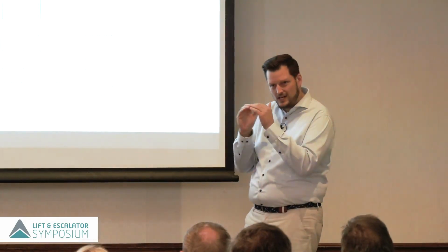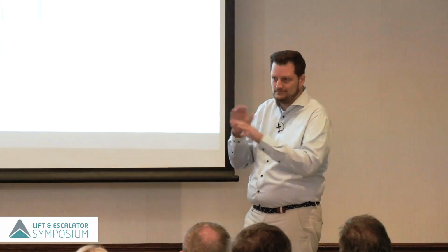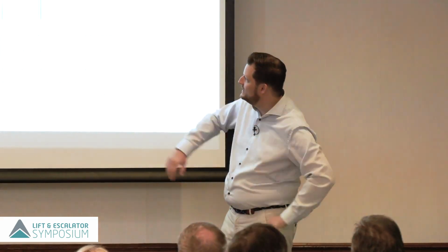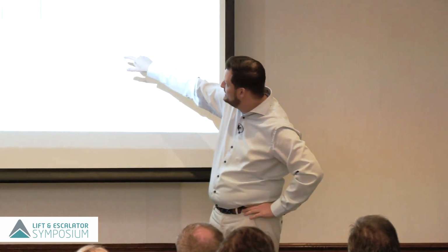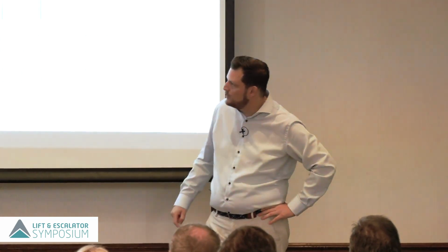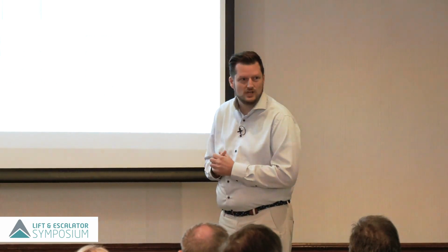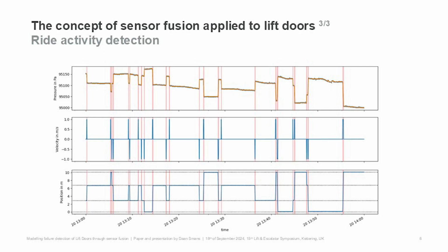Once it says, okay, I'm no longer sure if I'm on this floor or on that floor, well, the lift hasn't moved, so we're still on the same floor that we last registered with. Then you actually can get a position in meters that by now we've been able to get almost within the landing zone accuracy of 20 millimeters up and down, respectively. I think it's 1/4 of an inch under the SME, if I'm not mistaken.